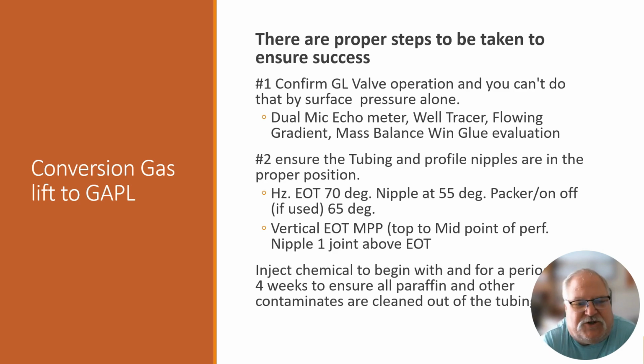Number 2 is ensure the tubing and the profile nipples are in the proper position. I always recommend end of tubing at 70 degrees. You can go to about 75, but somewhere between 70 and 75 in my experience has always been the best.